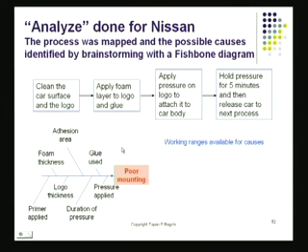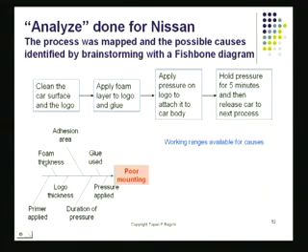With this map in front of us, a brainstorming was done, and all the factors that could have led to poor mounting. See that red box there? It shows poor mounting as the effect. Various things that could have caused it, those are listed here. For example, foam thickness could have caused this. Adhesion area, the area over which you apply the glue, that could have also caused this. The glue used, that itself could have probably caused poor mounting. The primer applied, the primer that was applied on the surface of the car, that also is something that could have caused the logos falling off.